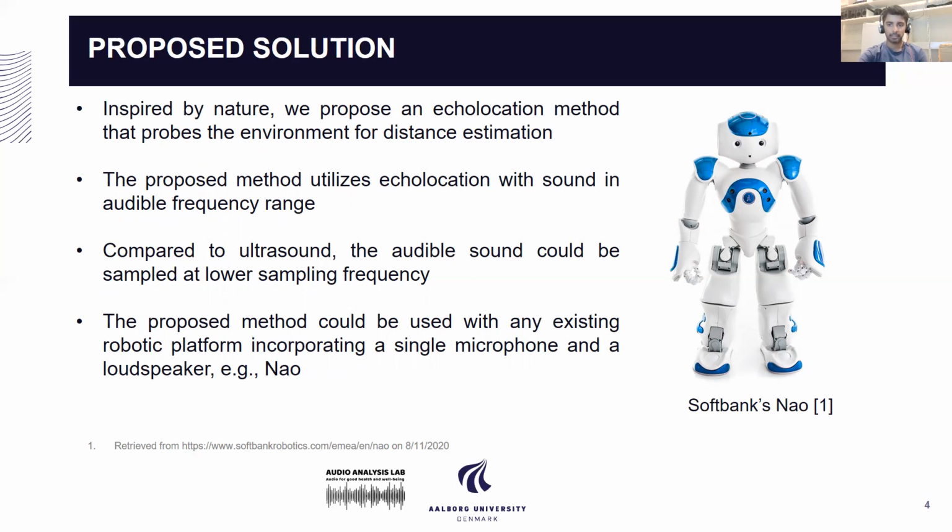Our proposed method works in the audible frequency range, which gives us an advantage over ultrasonic range sensors that require specialized hardware and a high sampling frequency. Moreover, our proposed method could be used with any kind of robotic platform as long as it is equipped with at least a single microphone and a single loudspeaker. An example of such a platform is SoftBank's NAO robot.